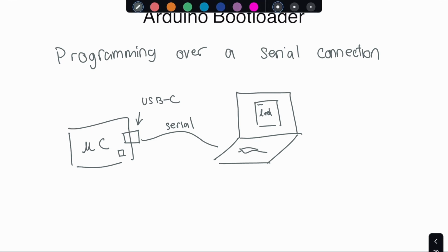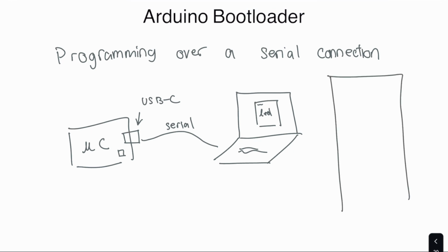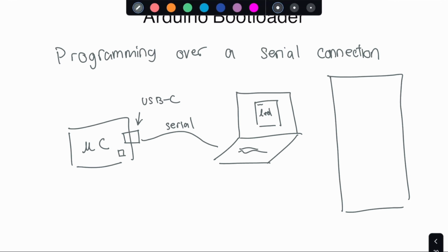And so back to our picture of memory, you have your application existing somewhere in there, and Arduino has its code running in here, and the original bootloader is running on here, or only running at startup, but still existing in memory. The Arduino code is then able to override yours with a new version of the app whenever you hit the upload button in the Arduino IDE.